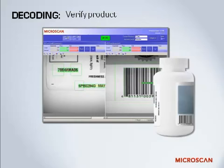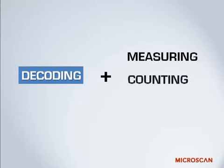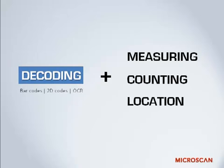An obvious question here is, why use machine vision to do this, when dedicated auto ID systems would do the same thing? You might think of machine vision as auto ID or barcode reading plus. The plus is the ability to run other measurements and operations in combination with the reading of barcodes or text. For example, you might want to read a label and also check that it's properly aligned to the product. In other cases, you may need the ability of a machine vision system to tackle tougher applications that require more capability in terms of image pre-processing, or in the case of a PC-based system, sheer speed and processing power.